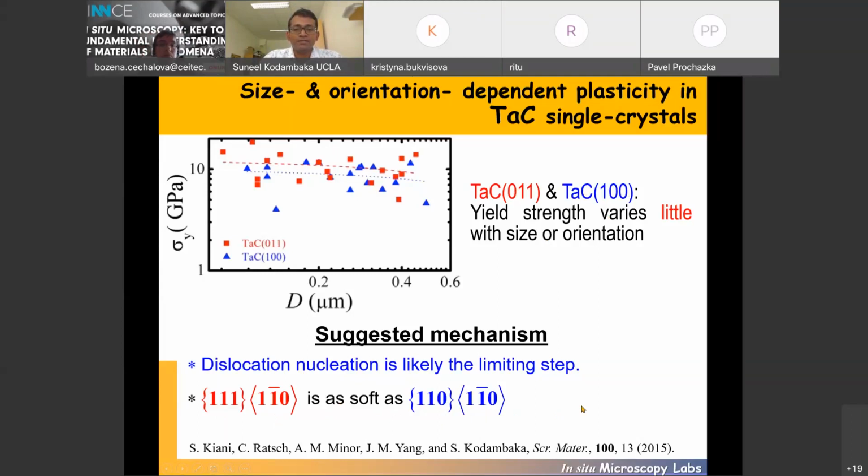And if you're not familiar with what is slip, just please let me know, and I'll be happy to explain what it is. It's basically, typically in most materials, it's the close packed direction where you would have the dislocation motion occur on close packed planes. But this is a sodium chloride structure, so in here 110 is the most favorable slip plane that is typically expected.